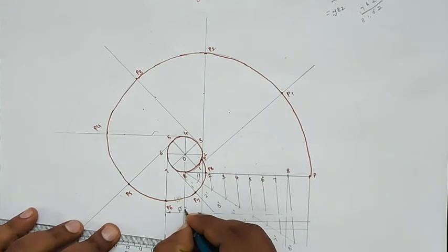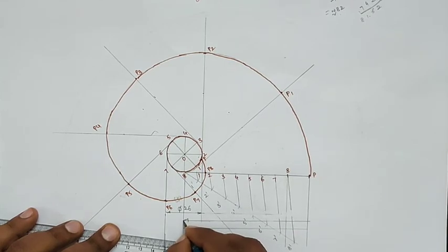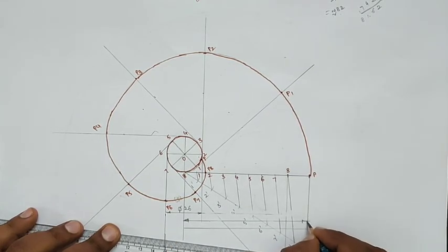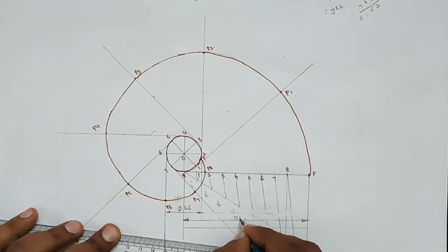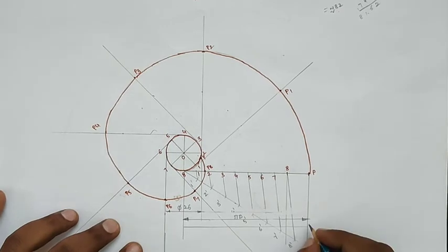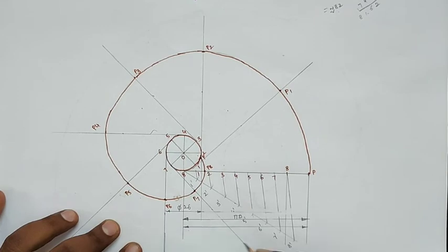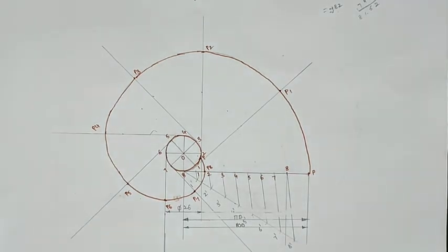The diameter they are giving is 26 mm, and the perimeter of the circle I am following here is 82. By using the formula pi d you can find it out, and the length of the string they are giving is 100 mm. We can represent it like that. So this is the involute of a circle. When the length of the string is greater than the circumference of the circle, we will draw the involute. So this is the last topic in the first unit. This was about the involute of a circle.